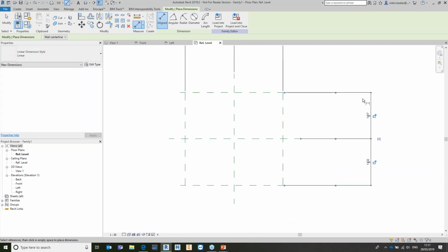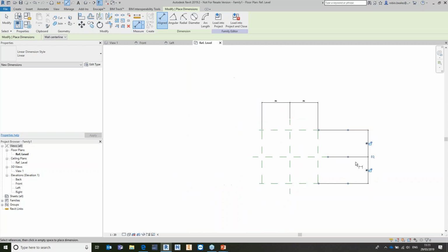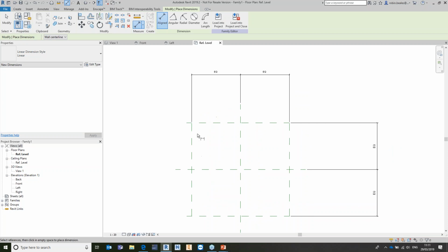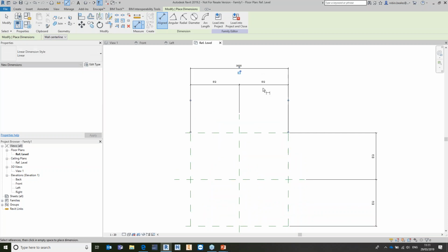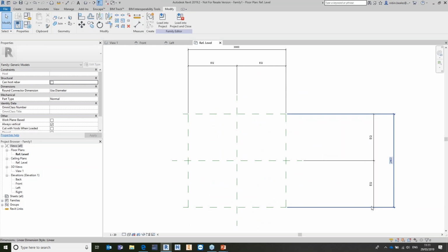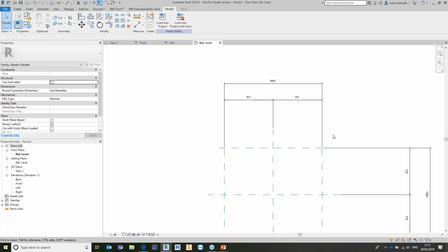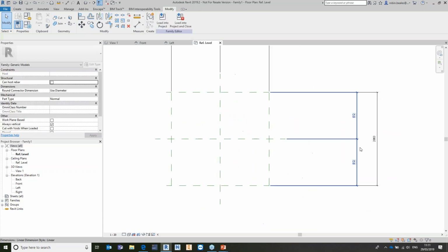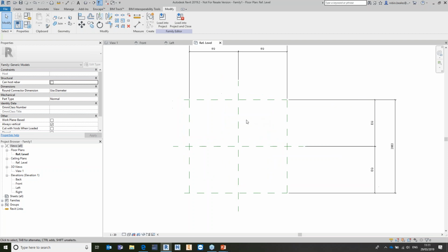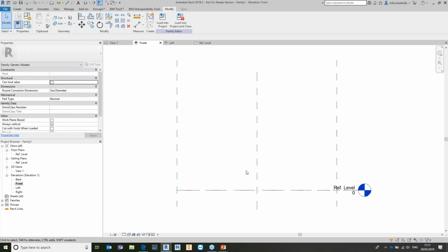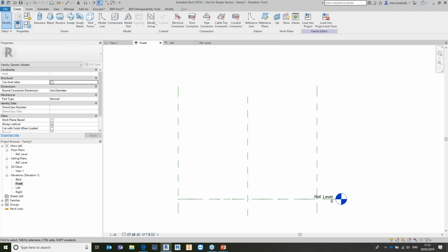Like I have 2 dimensions, I've created them at once, make them equal. I'd love to be able to do stuff like that inside of certain manufacturing pieces of software. But it works well. We go in and create some dimensions, and I'm just going to come in and say that I always want these 2 to be equal, and I always want these 2 to be equal. Let's say that I want this to be 3 meters by 3 meters eventually, and we'll just draw a very simple box. We'll go to the front view, and then we'll go and have exactly the same process on the front.